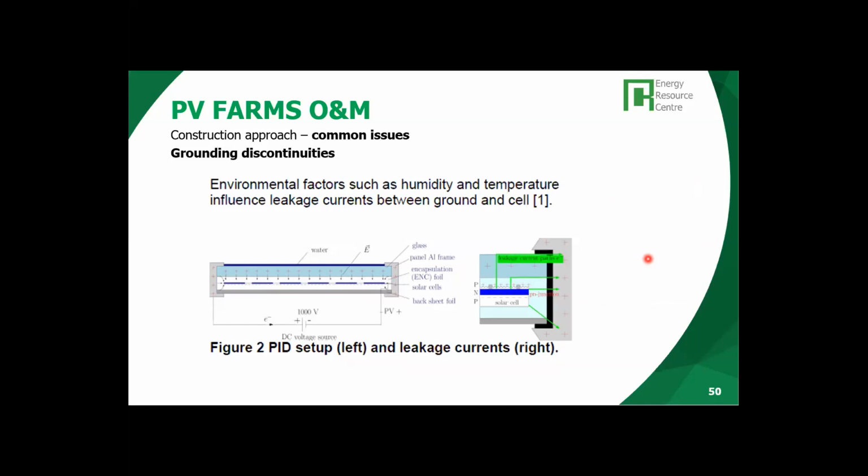Yes, this was the problem. First, remember the sentence of Paul: many times the quality of the earthing is not as important as its continuity. It's more important the continuity of the earthing. In addition to the electrical risk that it represents to the staff with access to the PV plants, the problems of the earthings can cause other problems.